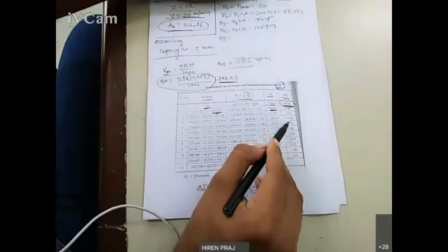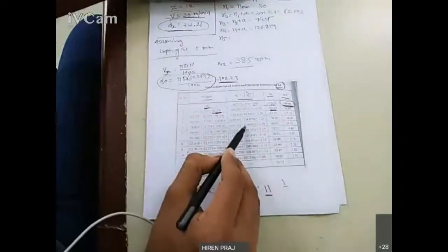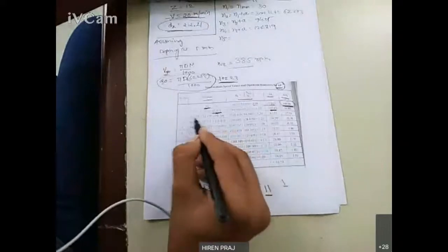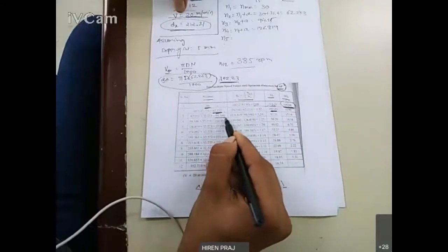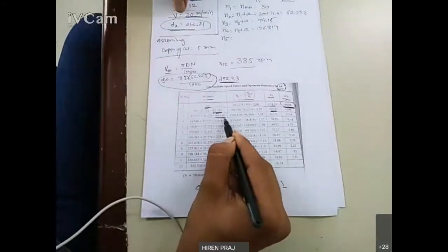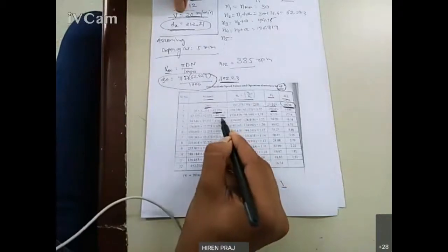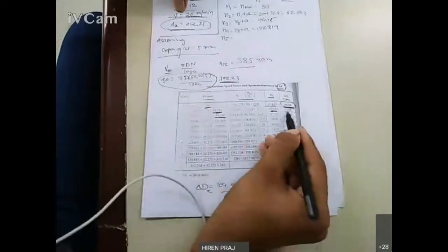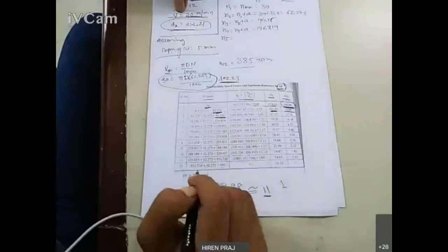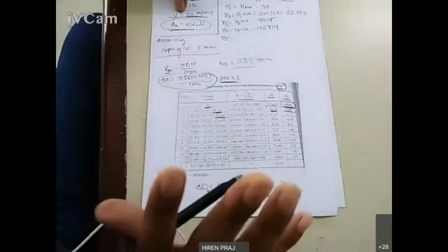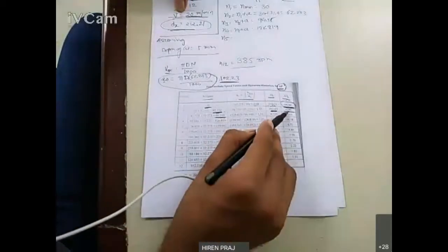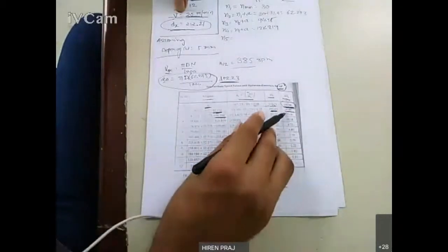Now you need to calculate this delta D for different speed steps. Suppose I want to achieve the required cutting speed and the available next RPM in the gearbox, that is N3, which we are getting as per arithmetic progression series, 95. Then how much material do I need to remove? That comes to roughly 35. My depth of cut is 5, so 35 divided by 10, roughly I need to go for 4 passes. So to change speed from N2 to N3, you need 4 passes. Likewise, you need to keep on calculating.